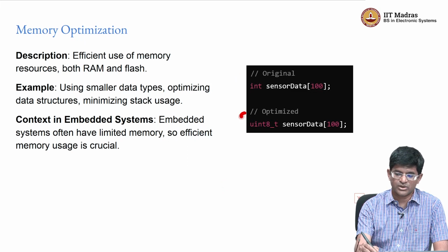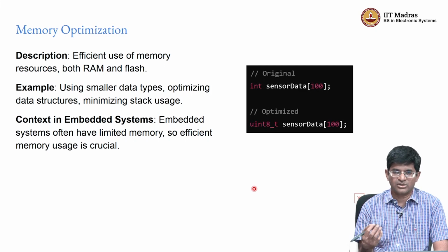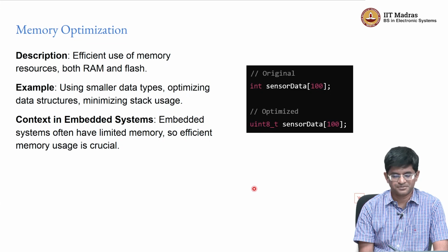In fact, if you can just do something with 8-bit integers, that's even better than doing something with actual full 32-bit integers, right? Not only does it occupy less space in memory, it also occupies less space in cache. It becomes easier to access, right? The strain on your bus when you're trying to load or store data is less. Strain, of course, being a not quite accurate term, but the point is that you are requiring less toggling of the bus in order to access the data.